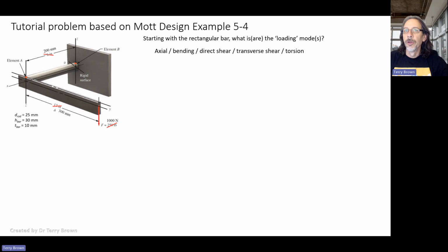Right? All right, so what have we got in this beam here? Right, there's no axial loading. Bending, right? So we've got a lateral load out here, supported at the other end. So we've got kind of a cantilever bending going on there. No torsion, no direct shear, but we do have bending. So we may have, and we will have, transverse shear developed in the beam. So we're going to do a bit of revision and look at what you studied back in Mechanics of Solids, Fundamentals of Mechanical Engineering or Applied Mechanics and Design A.